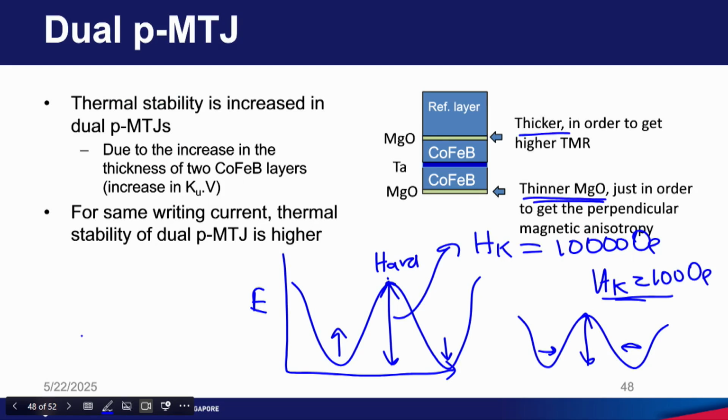So in the case of TMR, when you want to read information, we design MgO thickness to be around 1 nanometer, maybe plus or minus 0.2 nanometer. So this is the thickness of magnesium oxide here. If you make the magnesium oxide too thin, you may have pinholes. Some region of magnesium oxide may not be sputtered, so you will have pinholes, there will be no tunneling, so TMR will be affected.